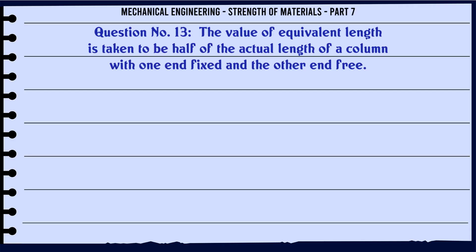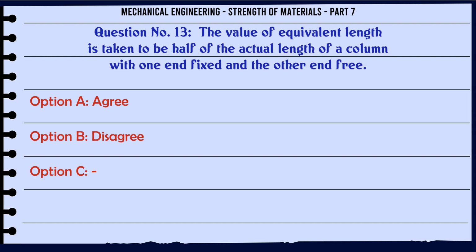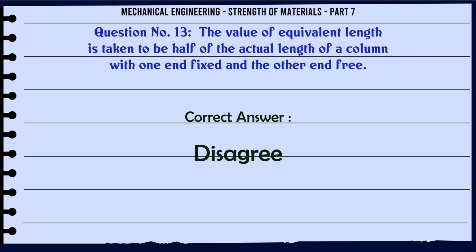The value of equivalent length is taken to be half of the actual length of a column with one end fixed and the other end free. A. agree, B. disagree. The correct answer is disagree.